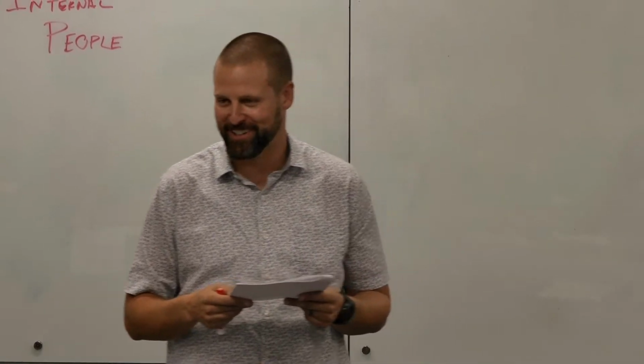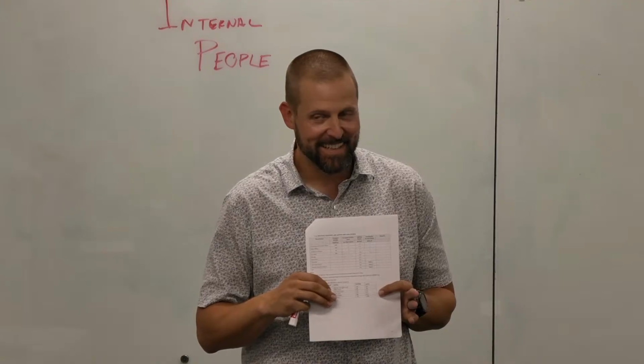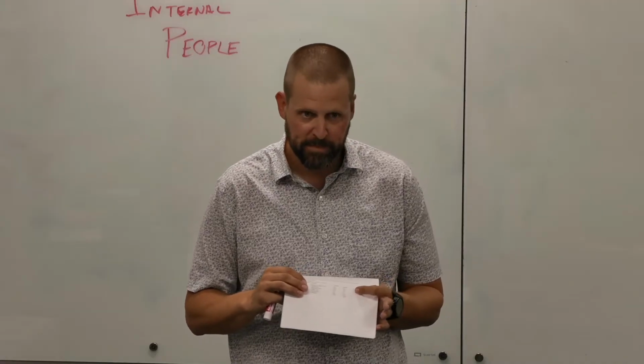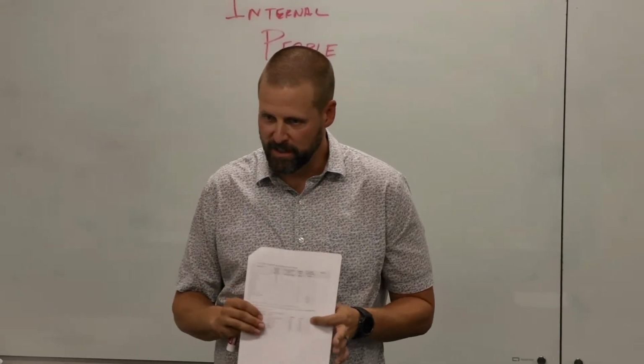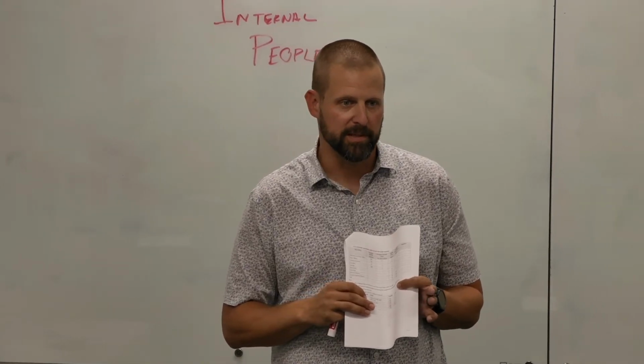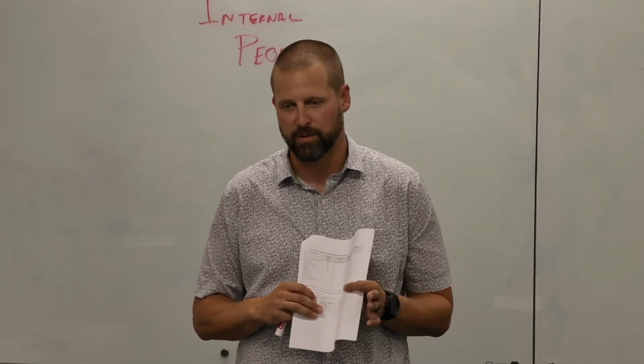And number two is often seen as 250, 200 instead of 245, 205. So these numbers are sometimes a little different. Usually when we use office work, we use 250 sensible and 200 latent. So in most of what we do, we use office work. The only time we do something different might be a lab where they're gowned up, or like a gym.